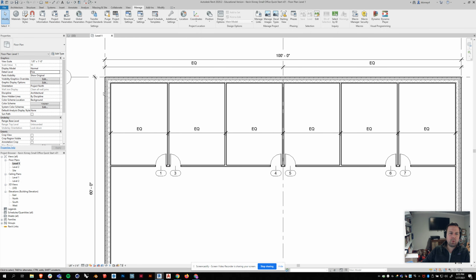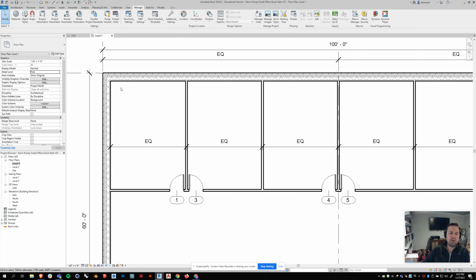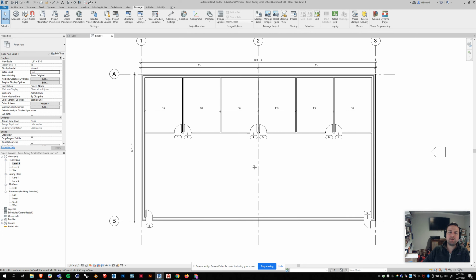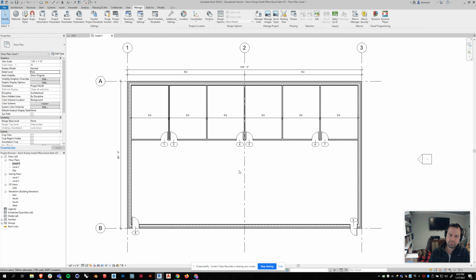There's nothing more important than line weights because it really shows what's cut and what's not. So in Revit, everything's built in, and in CAD, you sort of had to do that manually, which is, of course, a really good exercise to go through. You have to do it the long way so that you understand exactly the rules that are set up in creating line weights and what they're setting out to do. I'm assuming you all know that because you were taught so well last semester.